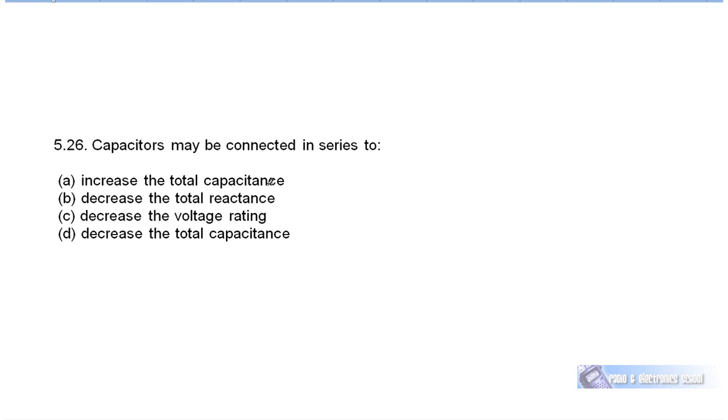Capacitors connected in series increase the total capacitance? No way. Decrease the total reactance? No way. Decrease the voltage rating? No way. Decrease the total capacitance. When capacitors are placed in series, the total capacitance is smaller than the smallest capacitor in the series circuit.